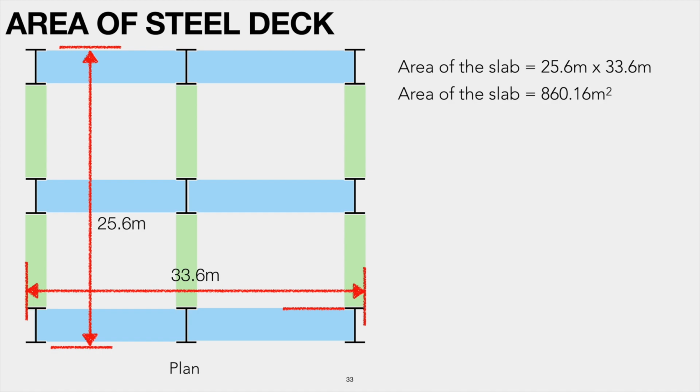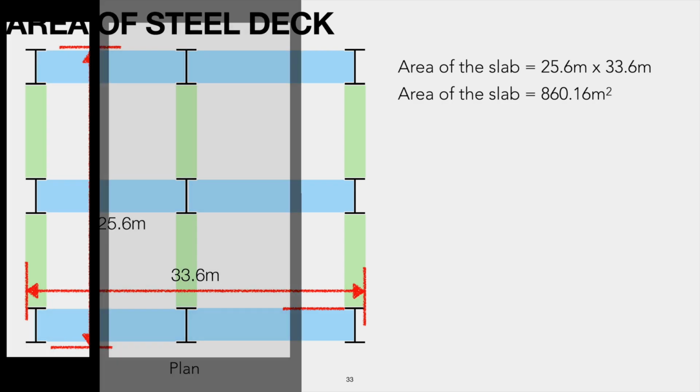Steel profile deck is a composite element amalgamated with reinforced concrete, and the unit of measurement is square meter as per the NRM2. Now you can see the calculated net areas of all steel profile deck in relation to this building.